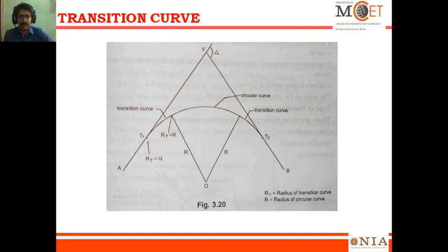I think you remember the centrifugal force. When the centrifugal force while turning is not governed, the two-wheeler or the car may be pulled directly opposite to the direction, and it may overturn and major accidents may happen. To overcome the centrifugal force in the opposite direction, the road will be raised and the portion of the road also widened, right? That is the purpose of providing this super elevation.